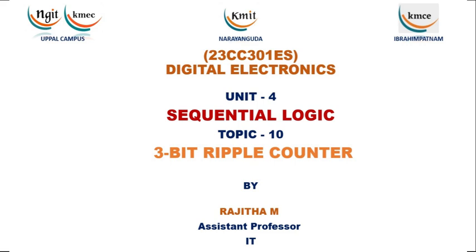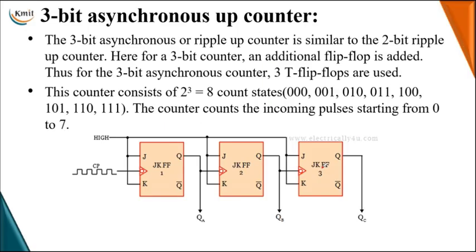In the last session, we learned how to design the 2-bit asynchronous counter. Now in this session, let me design the 3-bit ripple counter. In the last session, because it was a 2-bit counter, we used only 2 flip-flops. Here, to design a 3-bit ripple counter, we need 3 flip-flops, as each flip-flop holds 1 bit